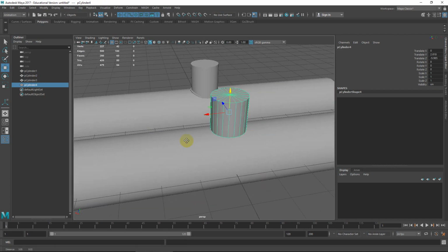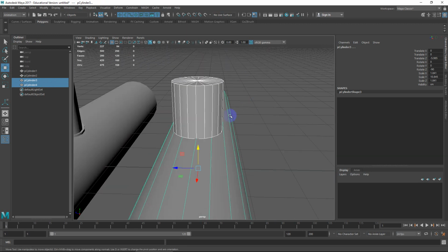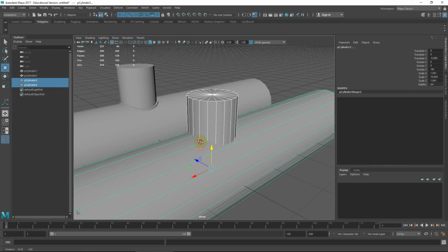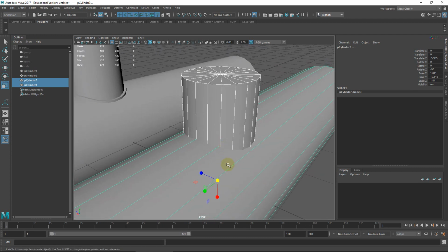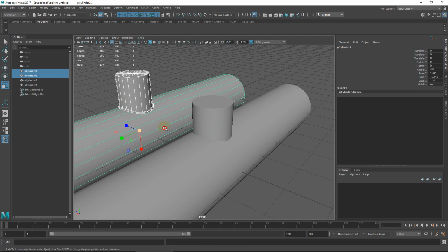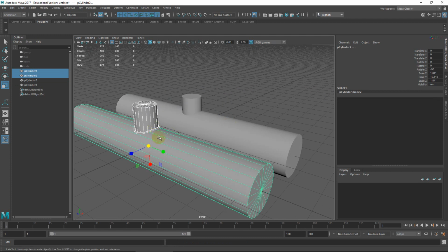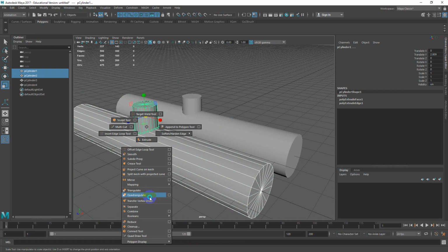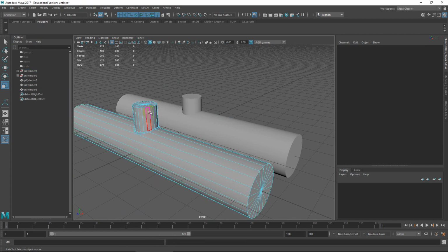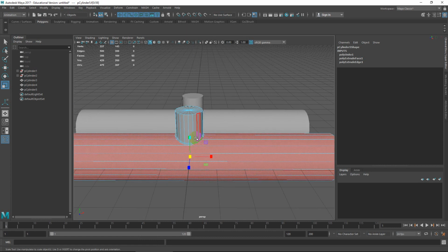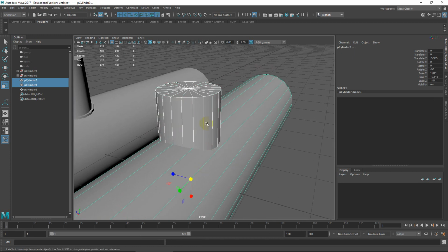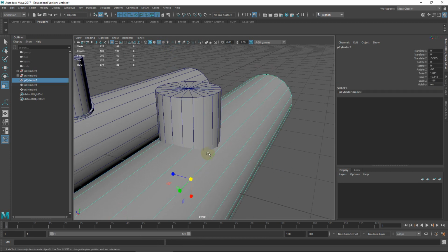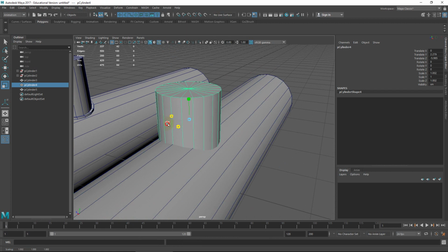As an alternate example, I talked about this a little earlier: Booleans. Booleans basically allow you to cut one object into another. This usually involves a little more editing. Sometimes there's value in keeping objects as separate floating pieces. Since I've deleted the history, I could in theory grab both meshes, shift right click, and combine them. There's still technically two separate pieces of mesh, but I can edit each one individually. If we wanted to combine them directly, I would look at the way the mesh lines up.